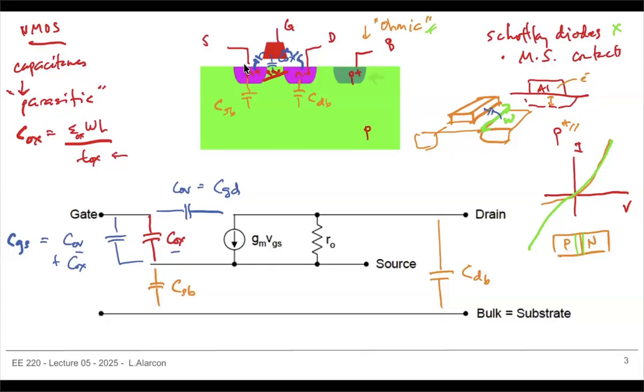If you plot voltage versus junction capacitance, when you increase your voltage across a PN junction during forward bias, the depletion region becomes smaller and you have an increase in capacitance. However, if you have a reverse bias and the depletion region becomes larger, then the capacitance goes down. So, for those who remember, it looks like that.